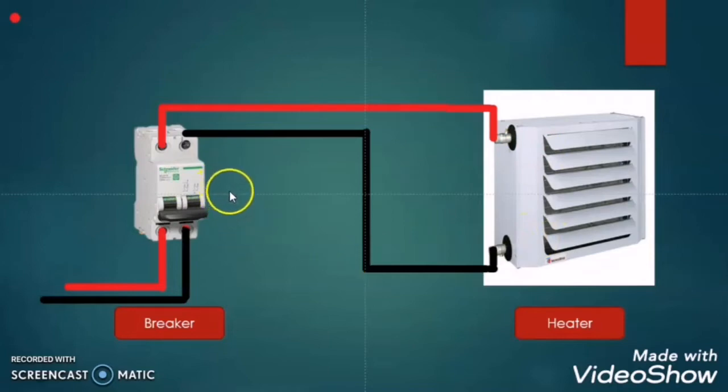So what we observe from here is that we can operate the circuit breaker whether the load is running or off. When we operate the circuit breaker while the load is on, it is called on-load operation, and when we operate the circuit breaker while the load is off, we can say this is an off-load operation, meaning the circuit breaker can be operated in on-load and off-load conditions.